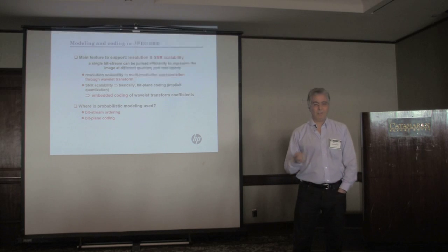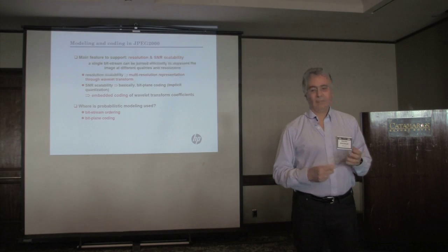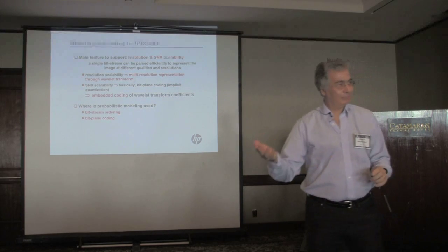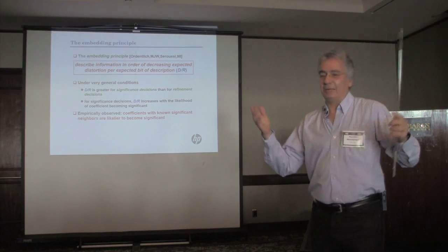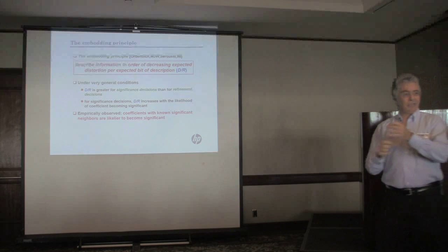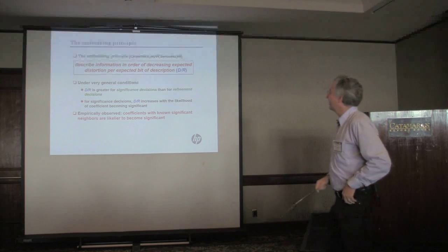I said you're sending a bit plane, but in what order do you send your data? In traditional cases, what you would send is bit plane by bit plane, and each bit plane, say, raster scan within a band. I'm talking now about each frequency band, not about the different frequencies.